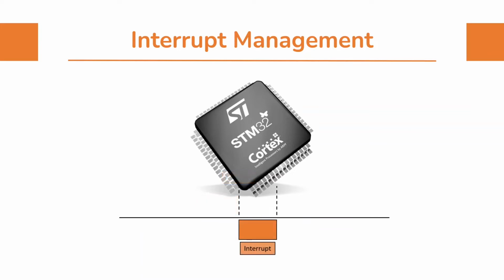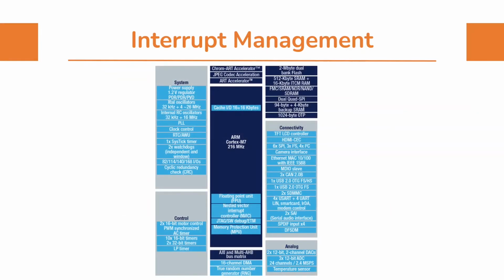In ARM architecture there are interrupts originated by the hardware and exceptions originated by software, for example, invalid access to a memory location. Cortex-M processors provide a unit dedicated to interrupt management. This is called the Nested Vectored Interrupt Controller, NVIC.